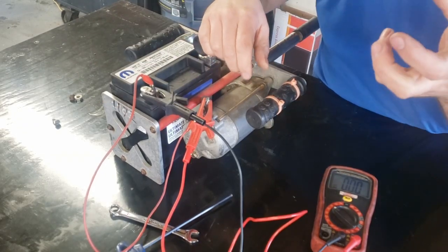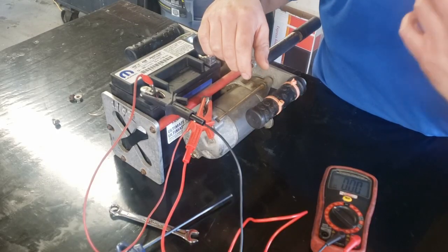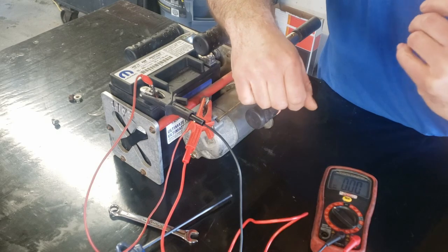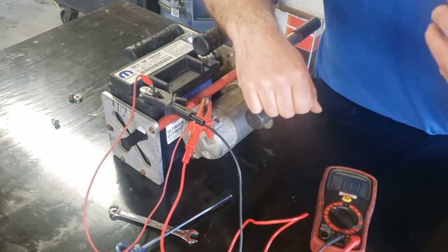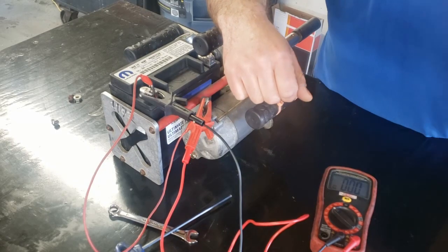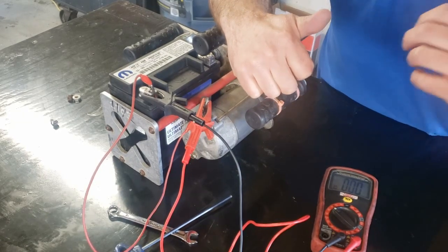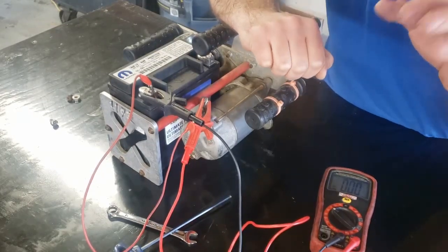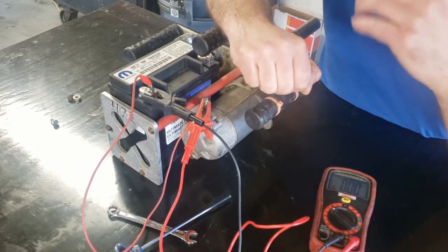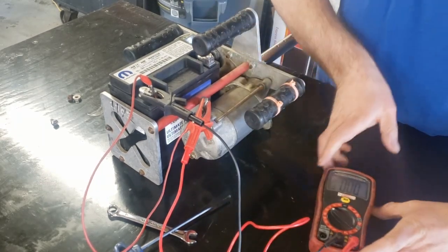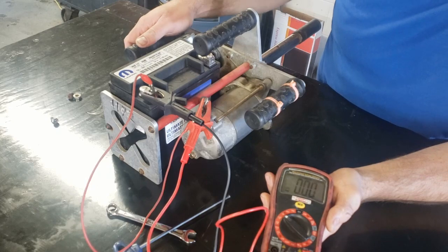What I'm trying to demonstrate to you here is what would happen in the case of a bad cable. Not that this wire is bad, but it's significantly undersized for my starter motor. Also, I want to remind you of the fact that there is no mechanical load right now on this starter. If there was a mechanical load, this starter would not turn at all. In fact, you're going to see it's going to run very slow. To not damage the starter motor, the battery, or melt the wire, I'm going to keep this test very short. So you're going to have to be watching the meter closely. I'm just going to bump this for a second.